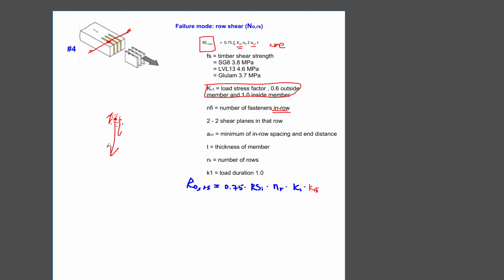In this case, if you have timber fibers far away from this dowel, this is the end distance over here, and your stress over here is near zero, and over here is a high concentration. The stress concentration is like a peak at this point, right?